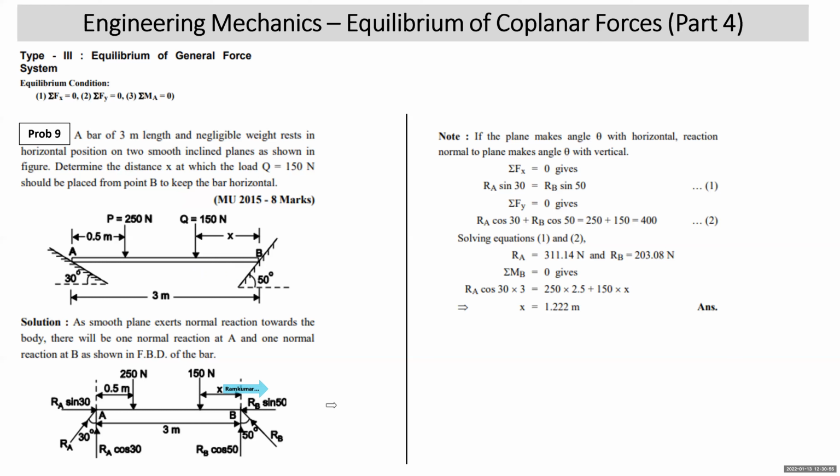Again, students, as a precautionary note, I am bringing into your notice that in a general force system, you should resolve the force exactly at the point where it is acting. Like if you are in a concurrent force system, you can resolve the force anywhere because you don't take moment. But in a general force system, the force has to be resolved exactly at the point where it is acting. So now my free body diagram is ready in all respects.